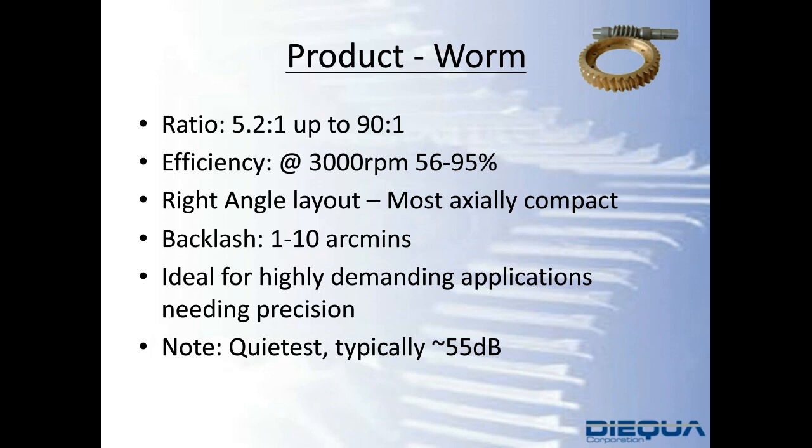If you climb your ratio up closer to 50:1, 70:1, 100:1, the only way you'll be able to backdrive is by damaging the gears, right? So if you've backdriven a 100:1, the question would be, what happened?